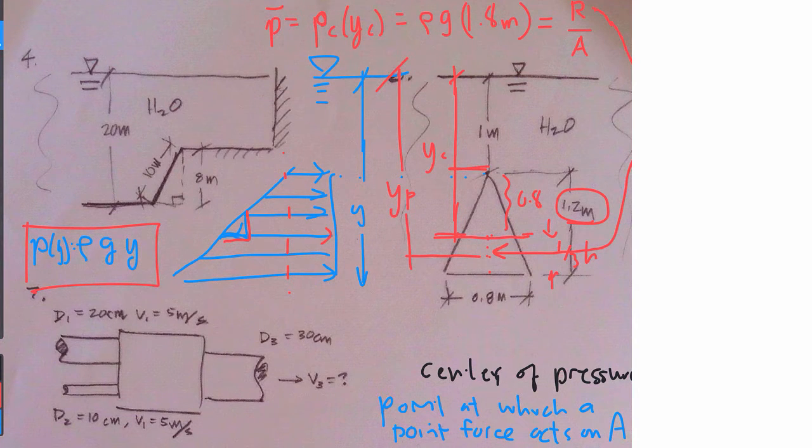And this is always a tricky calculation because, at least as I see it, the equations in the Fundamentals of Engineering reference are really confusing on this point. And I'm going to actually go to those equations in a second. Let's first calculate the numerical value of this average pressure. It is equal to 1,000 kilograms per meter cubed times 9.8 meters per second squared times 1.8. That's roughly almost 10,000 times 2, almost 20,000, we'll call it 18,000